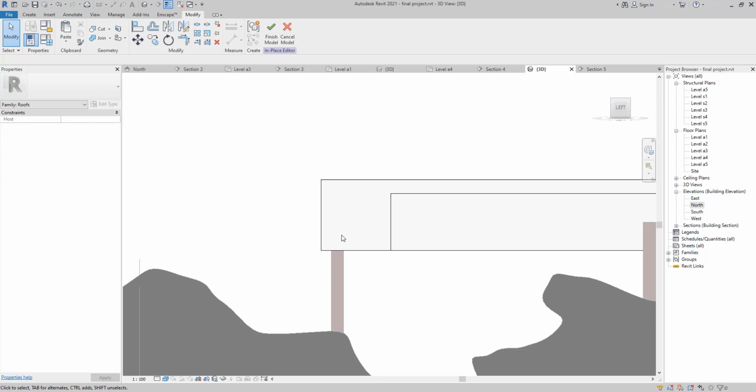For example, as I said, we can troubleshoot this box with a sweep in this way, or we can create two elements with extrusion. Extrusion is one good idea, but we are going to have one better idea which we are going to consider right now. Because if you use the extrusion system, later on you are going to have some problems. It might happen, but here the best option was sweep with a little bit of editing.